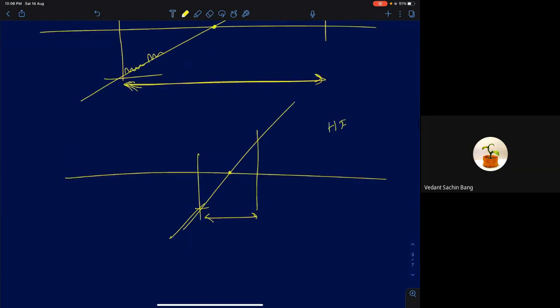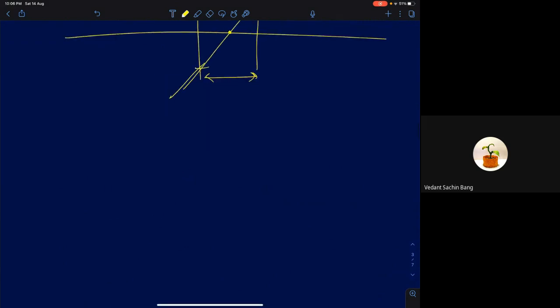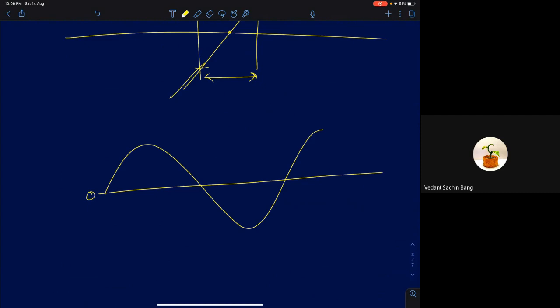So generally for higher frequency, that's why when I showed you the sine wave signal like this, what I was trying to tell you is that if you choose 0 as the threshold point, then the sinusoidal signal has the maximum slope at the origin. If I choose some other point away from the origin, the slope here, let's call it S2, and the slope here is S1. Obviously, S1 is going to be greater than S2.